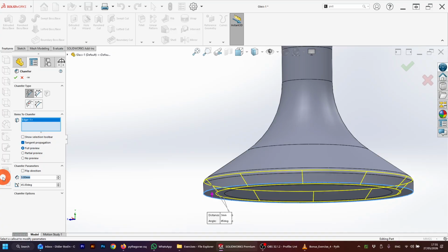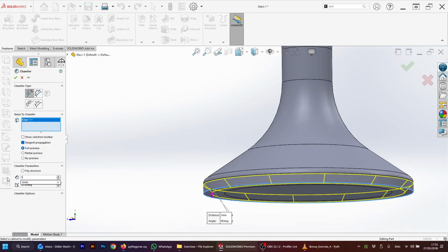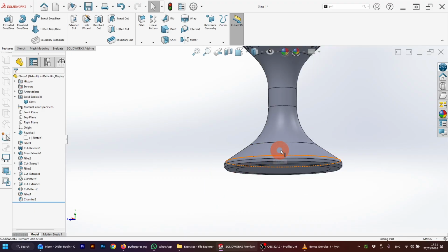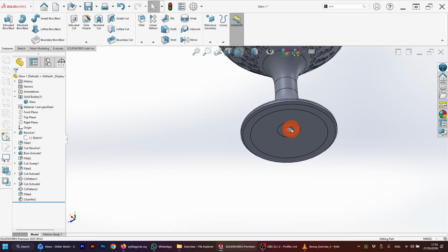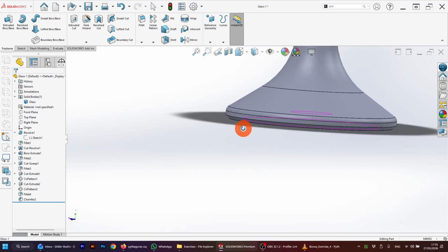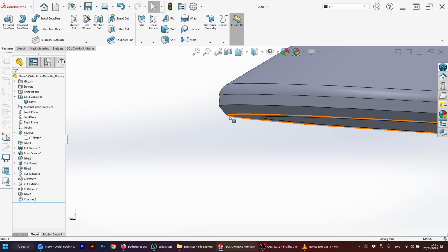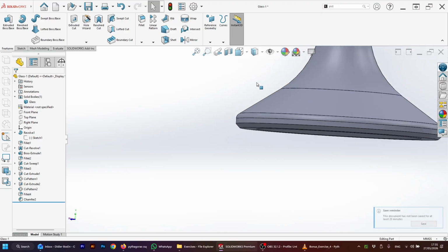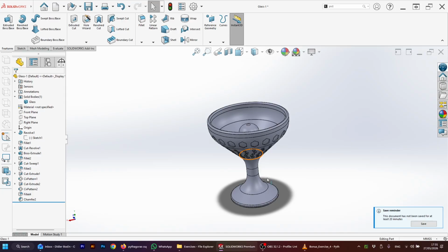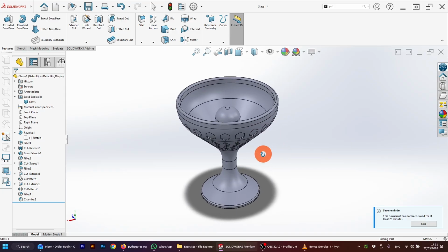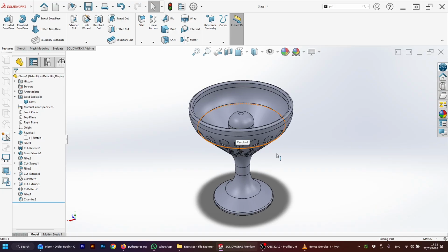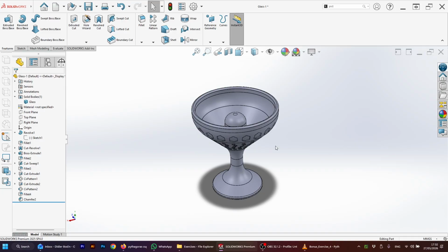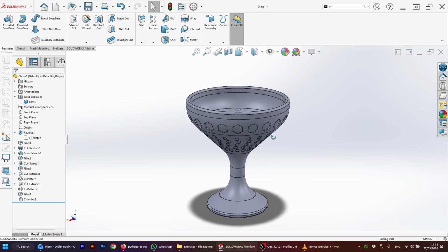That's too much. Reduce that to 2 millimeters, 1 millimeter even. It does bring a bit more detail to the product. What's good with chamfer is that the printer knows how to do sharp, going up sharply. Once you start to print, the curve is going back in, so that's no problem. But try it on your buttons: print it flat, print it with the fillet or with the chamfer. You're going to see the difference in quality, in roughness or smoothness of the surface that you want to get.